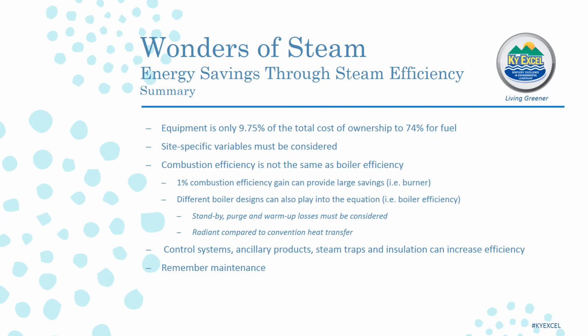Do not forget any maintenance requirements and costs. Proper maintenance will increase steam efficiency and will be around 10% of the total cost. Lack of maintenance can lead to failed products as well as dangerous conditions. Keep in mind, different boiler designs can have different maintenance requirements. Staff should be trained and licensed for the equipment so it can be operated in the most efficient manner.